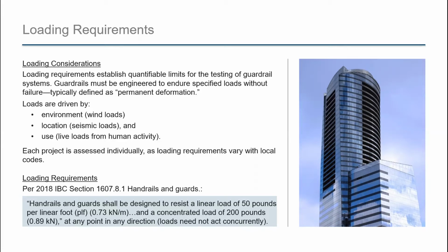In conclusion, loads are very important in the design of railings. They should be considered as early as possible in design, and a competent professional engineer should be engaged to make certain the building structure can adequately support the railing. Interior railings supporting primarily live load can usually be supported readily by most construction types. However, the use of thin stair treads or non-structural finishes such as stone or terrazzo sometimes prevents adequate railing attachment, so those details should be reviewed closely and in conjunction with the railing contractor.